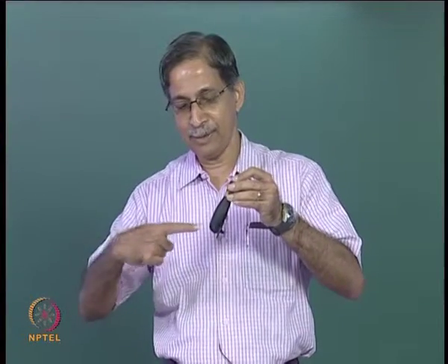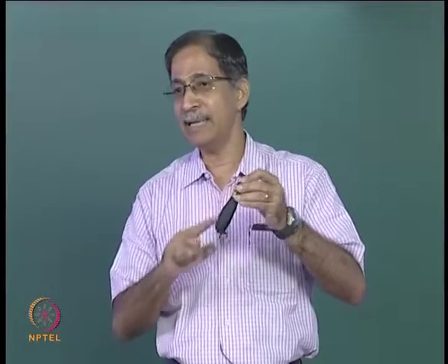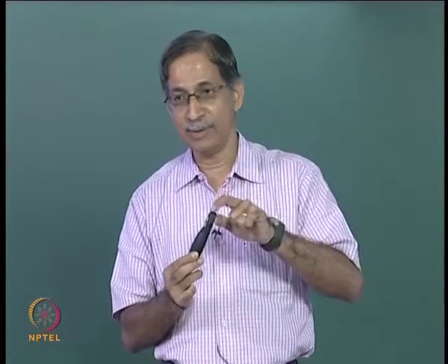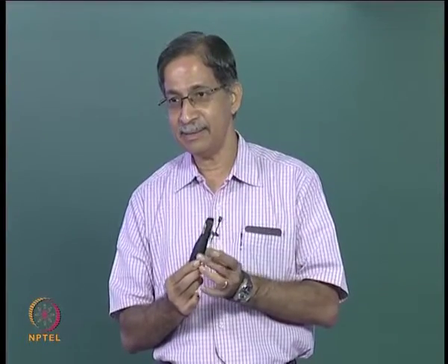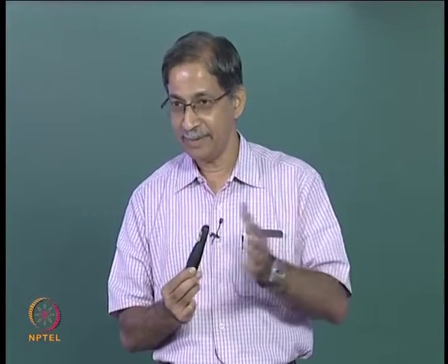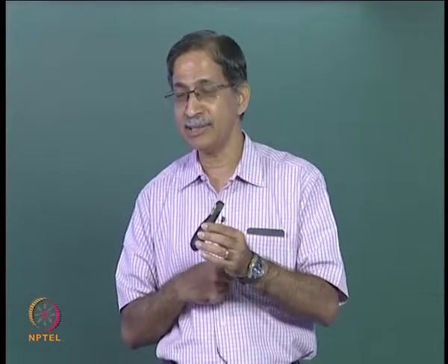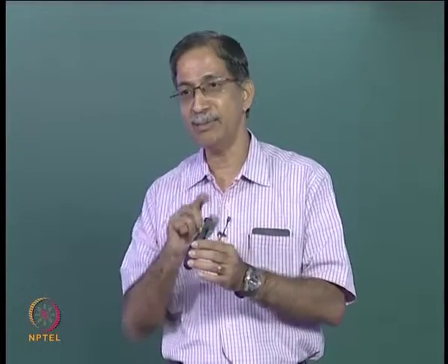So whether I push it this way or this way, I am going to get minus, but whether I pull it this way or this way, I will get this member elongating, plus. Does it make sense now? At the start node for the directions we assume you will get minus minus plus plus.